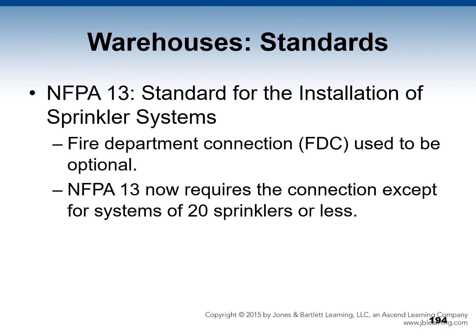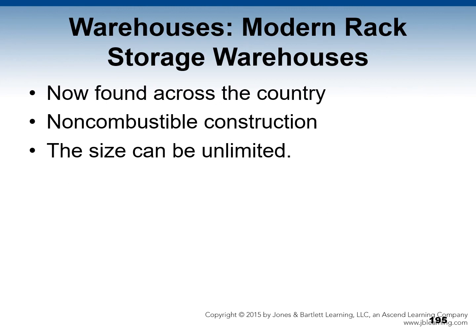NFPA 13 is the standard for the installation of sprinkler systems, and it applies to warehouses. The fire department connection, or FDC, was optional when this standard was written, but NFPA 13 now requires the connection except for systems of 20 sprinklers or less.